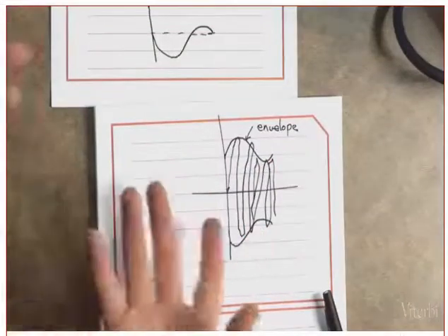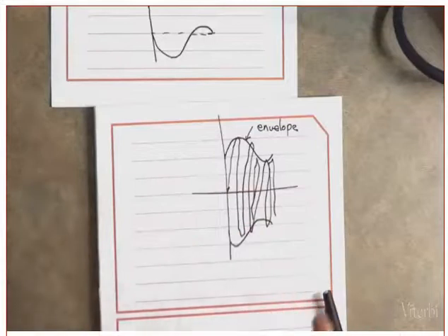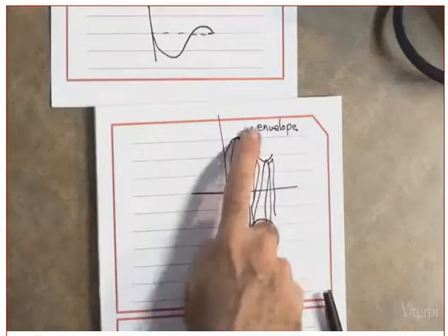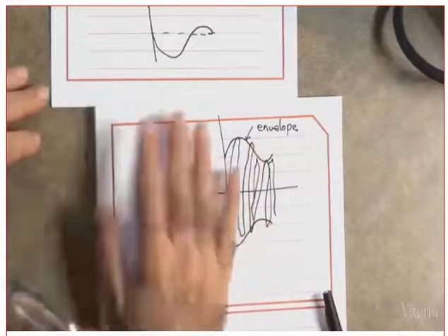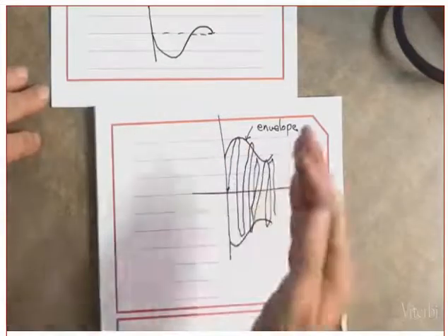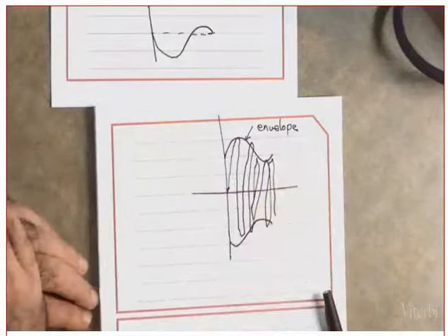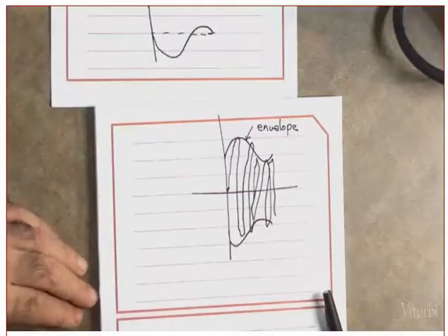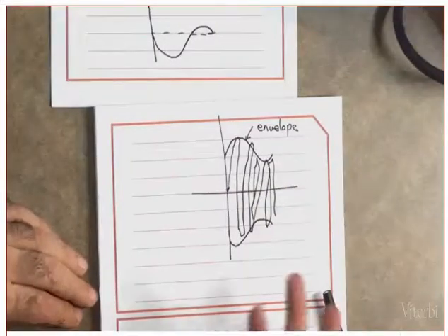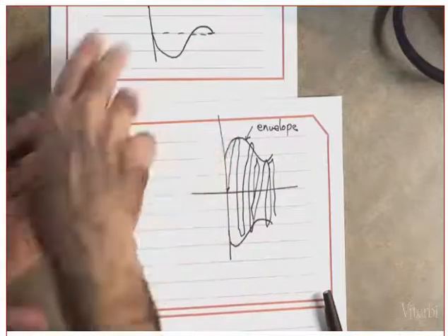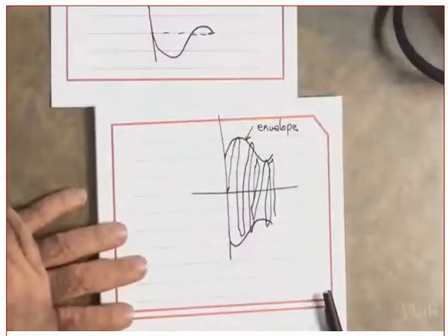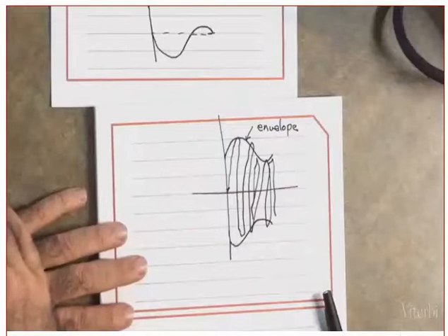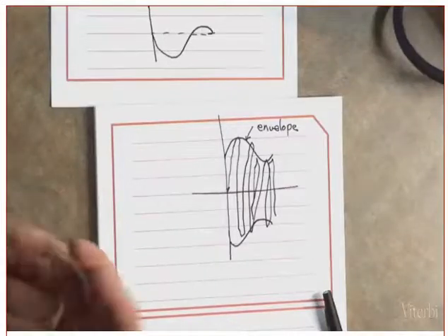No, it's not. It's shifted up, which means if I recover the envelope, how do I recover the modulating signal? Listen to the question. I need to put a DC blocking capacitor. Why? A DC blocking capacitor means that shift will be eliminated, and this one will go down again. Did you get my point or not? Yes or no?